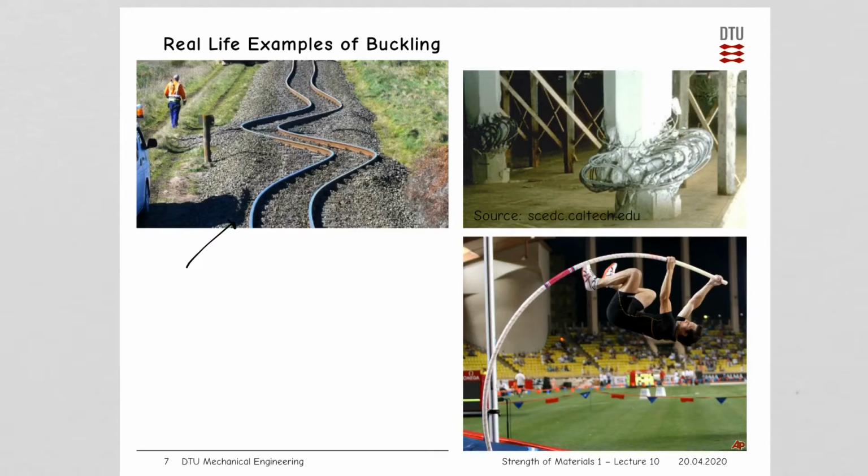So it will not be like bending, where we have seen that our deformations increase gradually with our load, so that when we increase the load gradually, we will have a gradual increase in our deflection. Buckling is a completely different phenomenon. So we will have nothing happening for a large force, and then suddenly when the force becomes too large, the structure will snap and bend to the side. So this is what we see in buckling here.